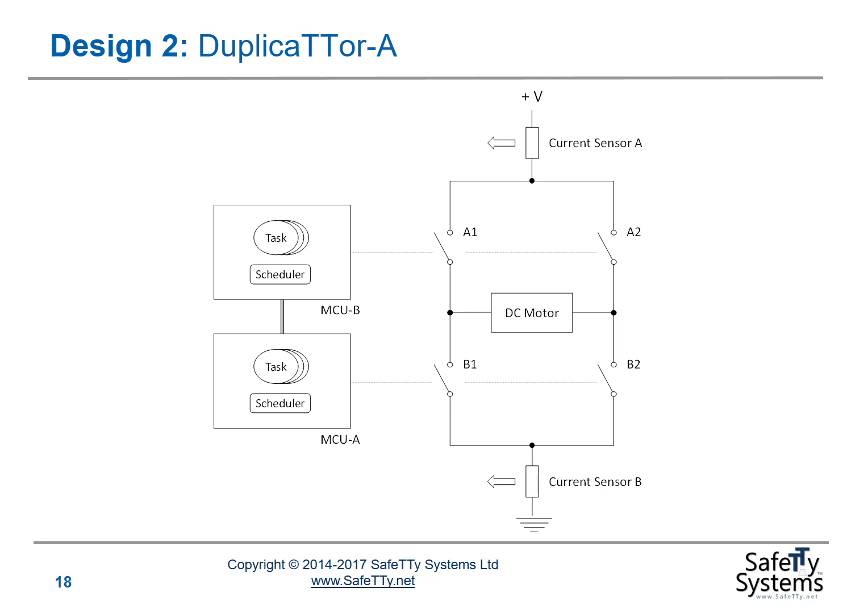So now we're using two microcontrollers, probably ASIL B microcontrollers, which themselves would be of lower cost, and we're giving the microcontroller B, for example, control of these two switches, so that, for example, if microcontroller A fails completely, then microcontroller B can still completely disable power from this system.